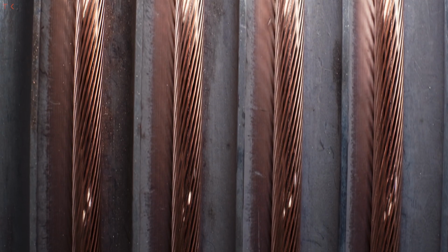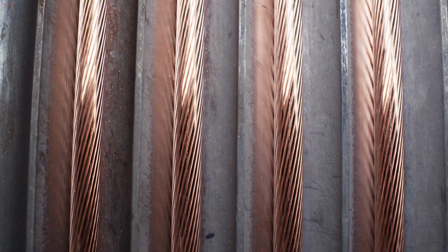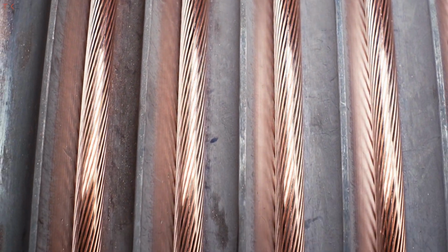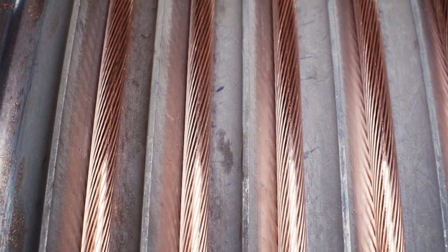Yes, you can put the optical DSP again into the same application, but the power consumption is not coming down. Latency is going to get worse, and it's going to get a lot more expensive. eTube essentially is a perfect replacement for copper because we're going to be able to do it at a cost structure very similar to copper cabling today, but we can provide the same solution for 1.6 terabit at 3 picojoules per bit. What that really means is that you're going to get very, very low power consumption.